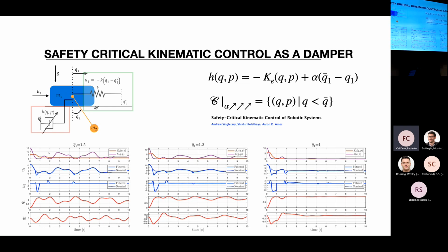It could be, what I'm saying is, for example, locomotion, you may want, and of course you can define it by the proper definition, but you don't want this to dissipate. You may want something that, you know, keeps the energy but bounces within a certain region. Yeah. Okay, in that case, you would rather have a kind of elastic compensation, non-linear compensation, rather than a damping.